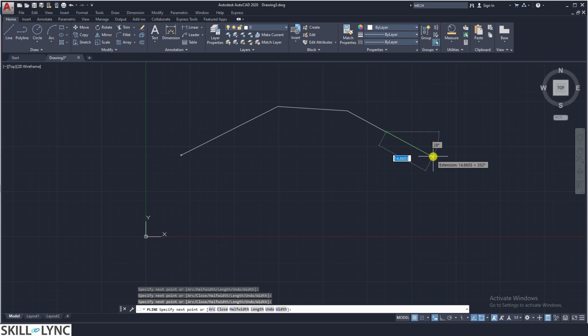Next you can extend it through the arc command. Once you click on arc, your arc options get included here. Whatever the first point that you have given will be the start point. Next it expects a second end point, whereas you can also specify the angle or modify from the end point to the center point.